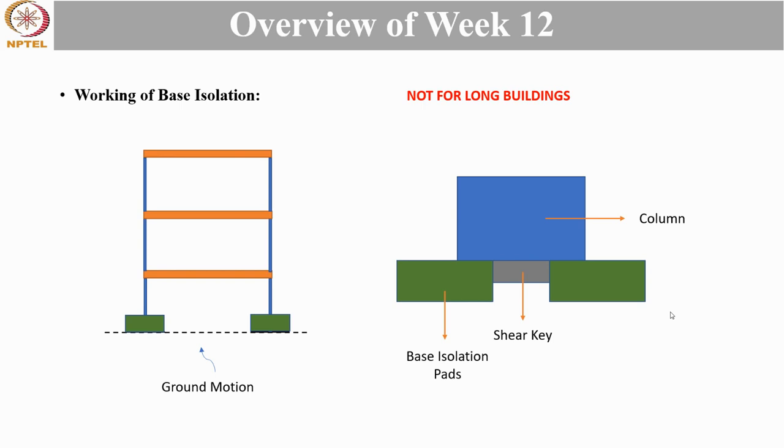However, now these base isolation techniques work very effectively, but they are only applicable to low-rise buildings and not high-rise buildings. Why? Because in low-rise buildings there is mainly shear deformation, but in high-rise buildings due to vibration there can be buckling and other motions also, due to which there might be tensile forces on the isolation pads. Now, as the shear key doesn't take tensile loads, it can deflect from its original position and thus the whole base will rise, which is not desirable. Thus, the application is only limited to low-rise buildings, which are generally 5 to 10-story buildings.